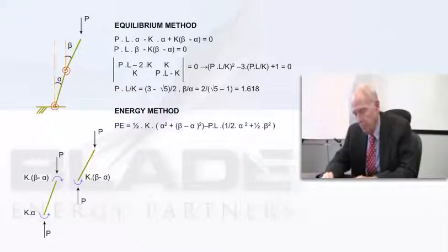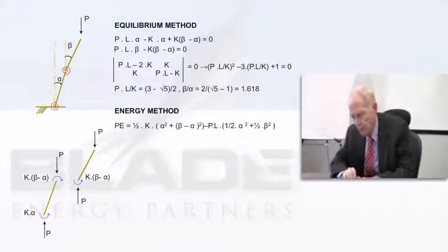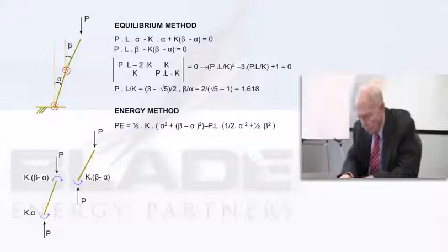So that means that if the variation of the potential energy is to be 0, which it must be, because that's one of the big theorems in mechanics, then the coefficient of delta alpha and delta beta must separately vanish. When I do that, I get the equilibrium equations from up above. But the more exciting result is to get the second variation.